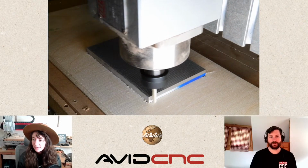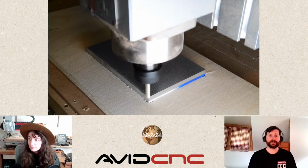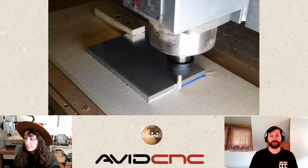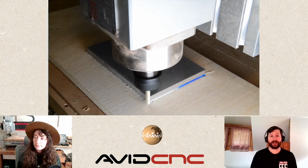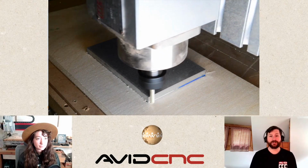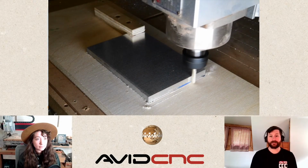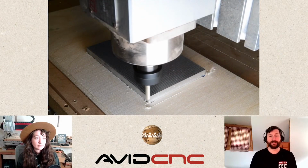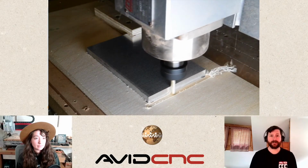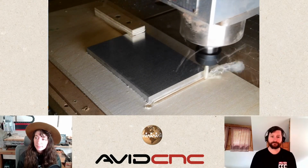Right. Yeah, and so this is without any lubrication. Whether it's compressed air or lubrication, if they encourage chip evacuation and your work holding fixture can handle it over time, I am always a fan of increasing your ability to have good chip evacuation. But if this were a jig that you wanted to use over and over again, lubrication wouldn't be an ideal scenario unless you change the material of the jig from plywood to something like another metal or plastic. Yeah, HDPE or something is a very common choice for that, right?